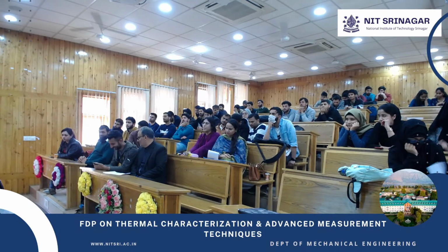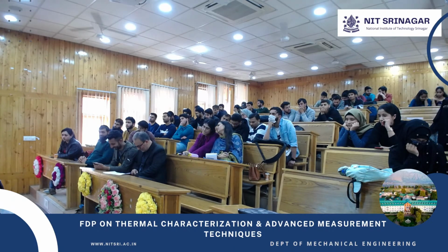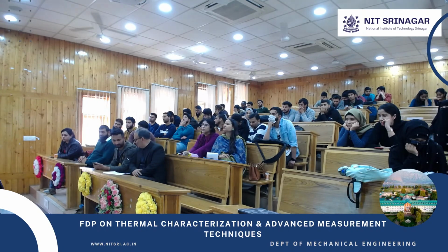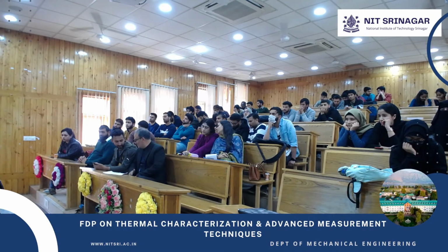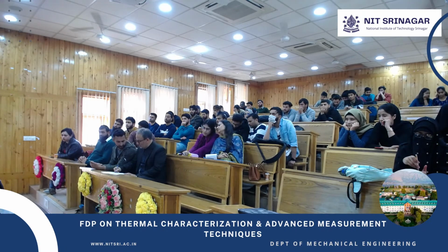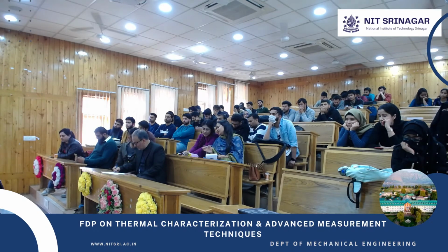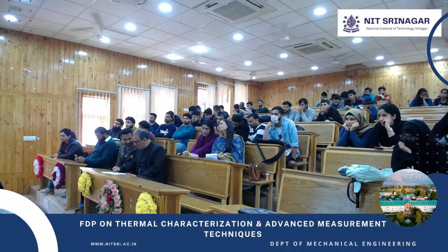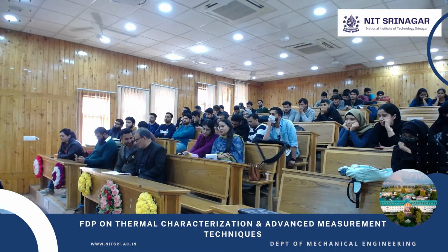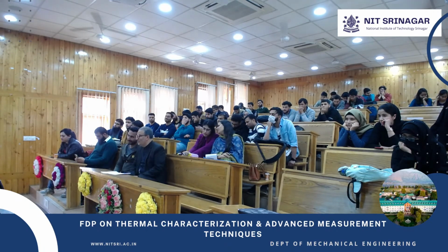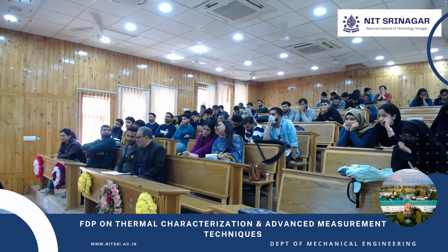Again, we have not directly jumped to the transient, rather we have approached with the conventional stabilized technique, that is the steady state. We did the experiment under carbon dioxide environment and under the vacuum environment, so that there are two ways of looking at it. One is spot conductance, another is gap conductance. Means when it is filled with the gas, gap conductance. Otherwise, we generally term it scientifically as the spot. So we have done a lot of exercise, a lot of experiments at different pressures, and we have found out.